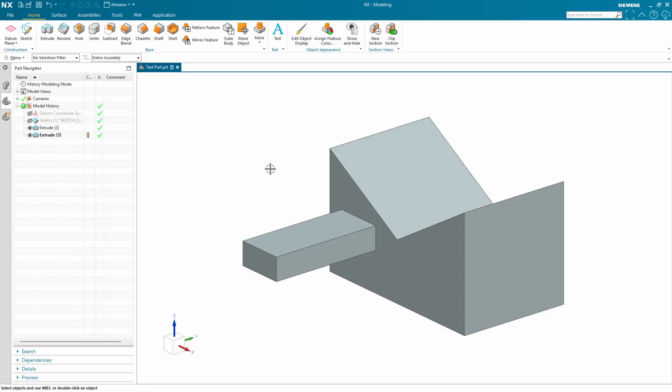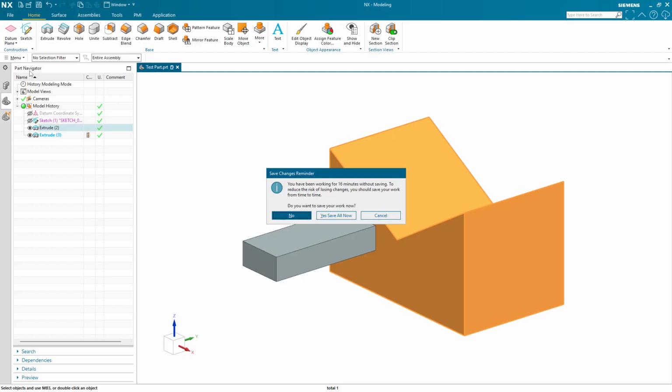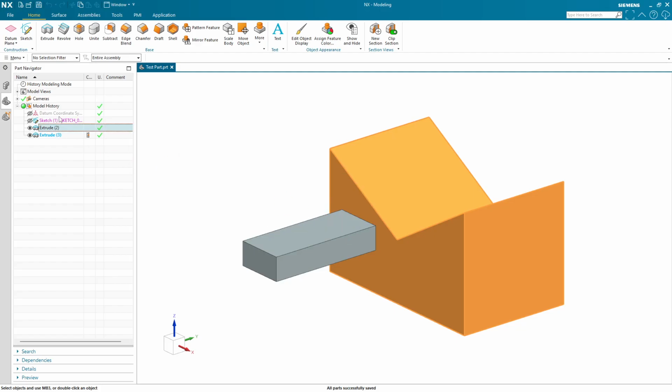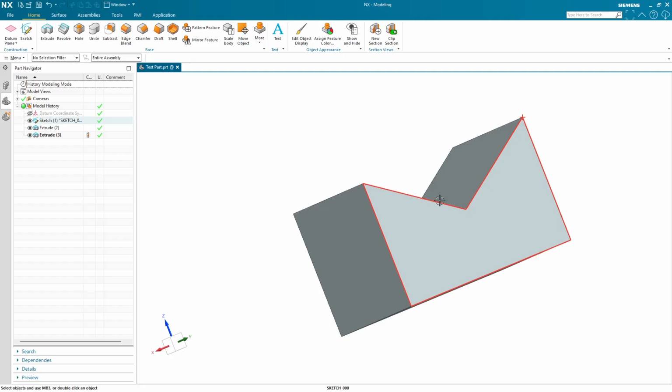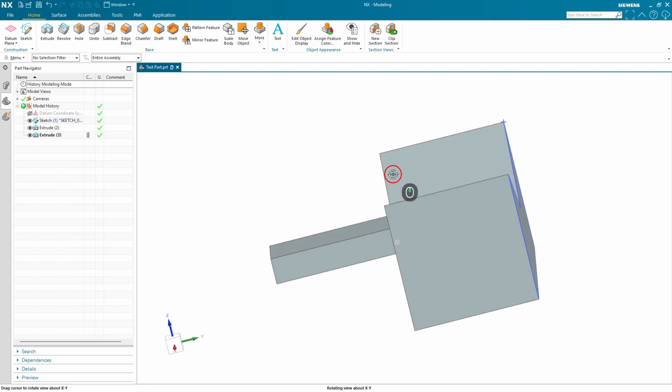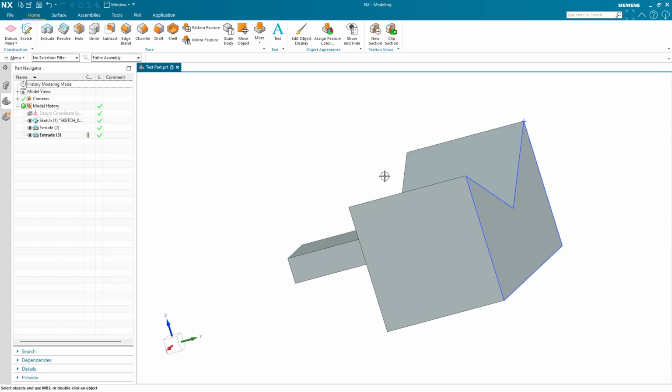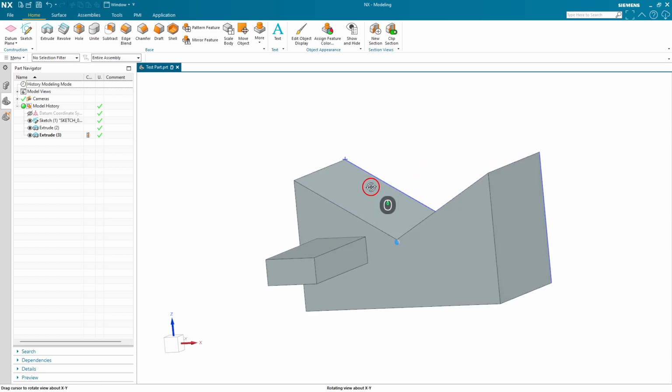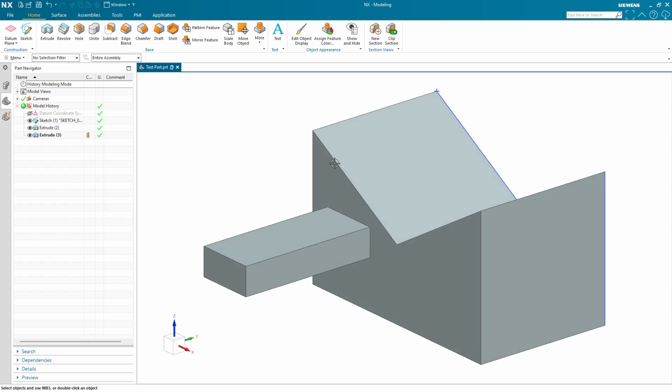However, my strong advice is to not do it that way, to have separate sketches from your extrusions, and although you'll have a denser part navigator, you will have an easier time accessing the geometry that defines your part and reusing this again later if you need to make other features that look like that or that are based on that. So that is my personal approach, spicy personal opinion, but do not make a sketch through the extrude menu, because when you do the extrusion, the sketch will disappear forever. Not forever, but it won't be usable.